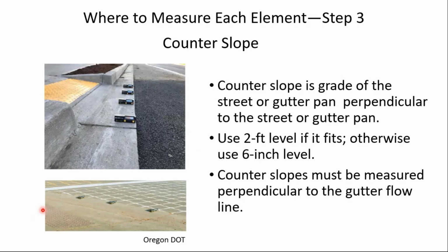What is the recommended offset from the edge of the DWS to the back of the curb? And he notes they like to use 2 to 3 inches where he works. Yeah, I was going to say 2 inches. I mean, I think 3 inches would be okay too. Obviously, you have to look at each specific situation, but I would strive for 2 to 3 inches. I think that's a reasonable guideline. Thanks, Ron.